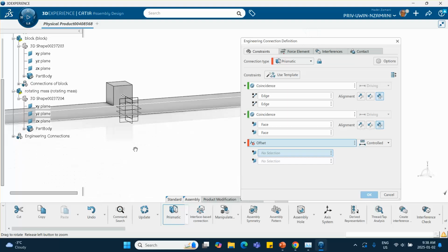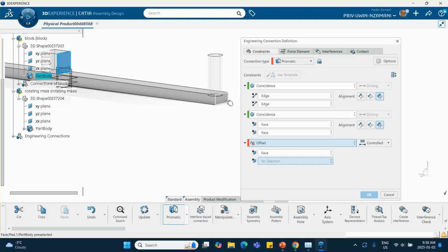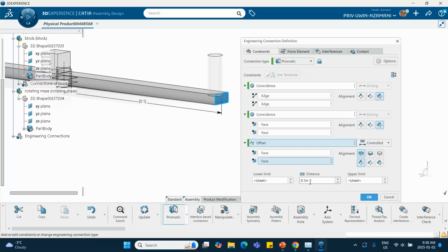And for controlling things, now remember, when you create a motor, when you create these velocity motors, you must have a command developed so that you can pick it. It's very important. You need to have a command for this prismatic joint and a command for that revolute joint in order to be able to pick where the motor is going to be. Here for the offset, I'm going to measure the distance from this end to that end. That's entirely up to me. So right now, that's what it is. Very good.